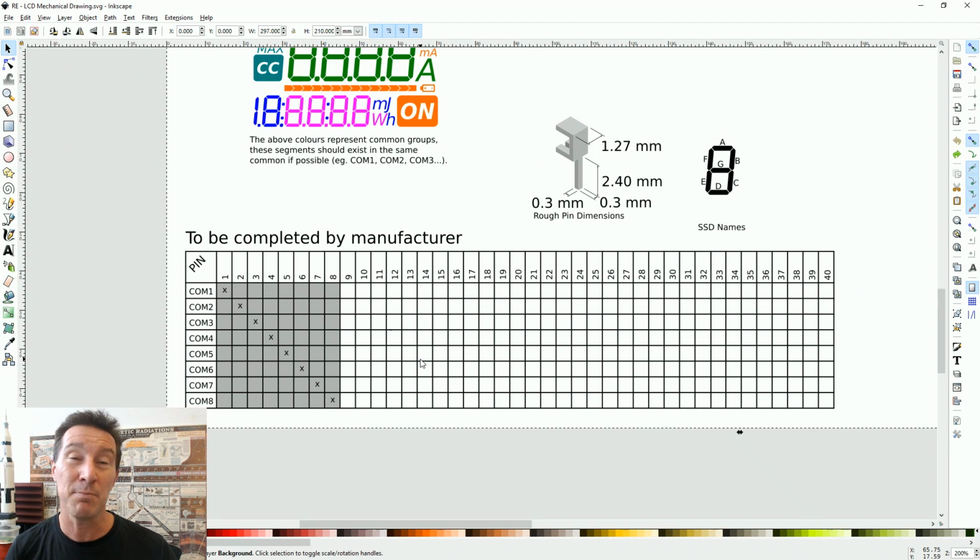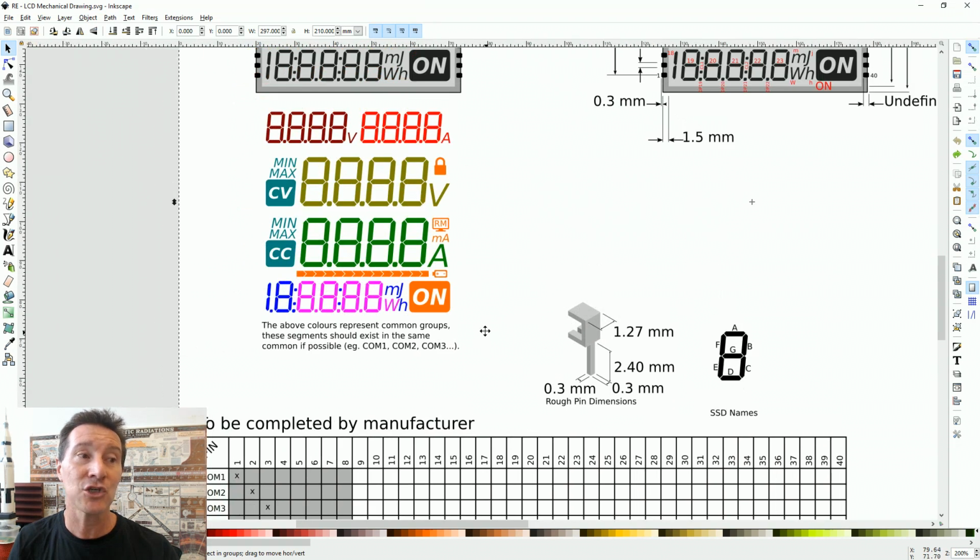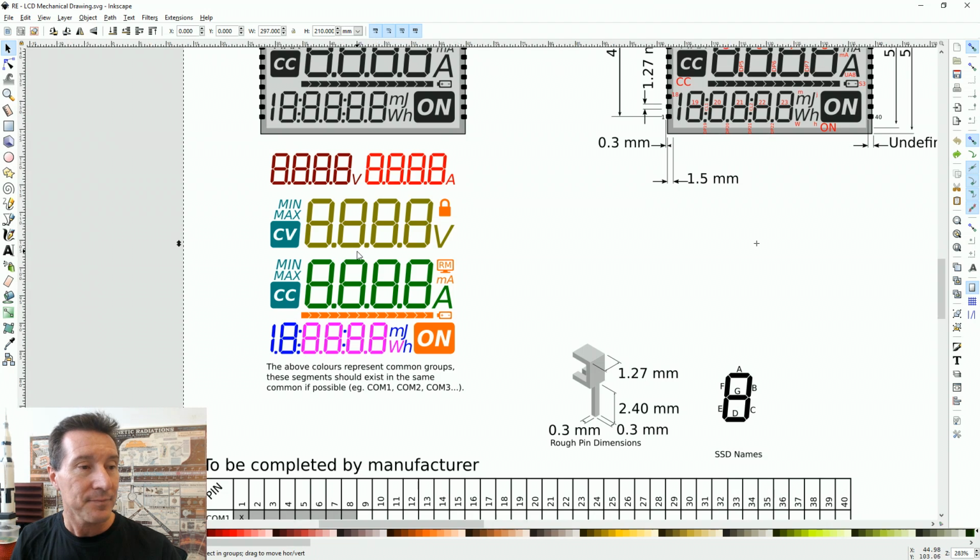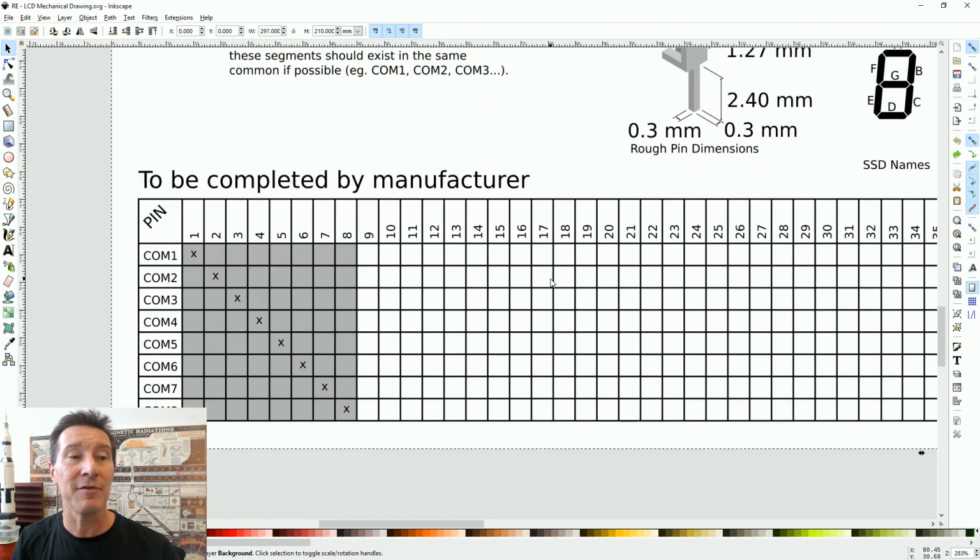We could, of course, hard specify which segment we want connected to which pin, but then it's like PCB routing. You can't just do it willy-nilly. You can't have one over here and 2 segments over here going into opposite sides. It just screws up the routing on the glass, because it essentially is like a PCB layout, and they manufacture these using layers just like on PCBs, and the photographic method with the conductive paths actually etched onto the glass itself.